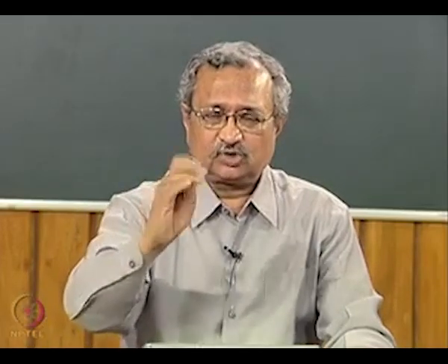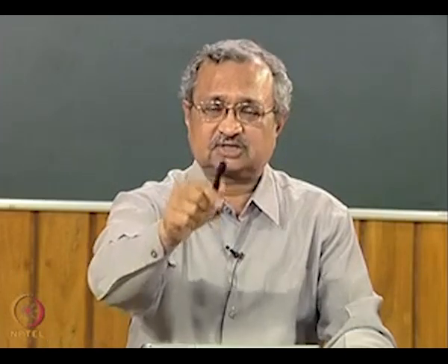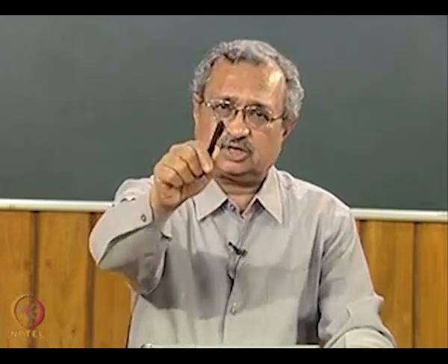So, the object of lower light intensity that I want to see becomes invisible or blurred. This is the kind of effect called the glare effect. As I cannot see the object of interest clearly because of the presence of a brighter, high intensity light source in the same plane, it is disability glare. Like in this figure, there is a heavy light source, and if I want to see something here, then it becomes blurred or I cannot see it properly.